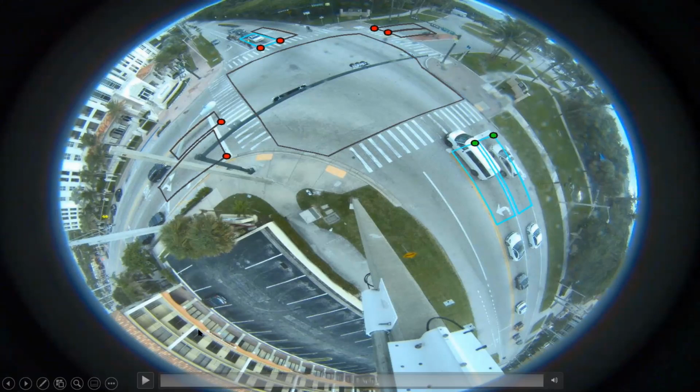Hey, Justin, we have another question. Can I have pedestrian zones without vehicle zones? Yes. If you wanted to just draw an intersection with only pedestrian zone, you could do that and then provide outputs into your controller for extending those vehicle phases. Yes, that would be possible. An example of that would be maybe a HAWK crossing mid-block where you wouldn't have typical detection. However, maybe you would want to exclude vehicle zones and for a particular reason, you would be able to set it up in that manner.